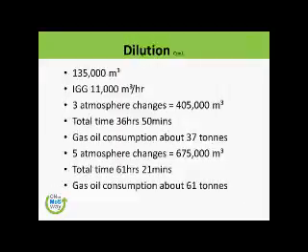So now we have already talked about the displacement process. Now we are giving you some hard facts about the dilution process. In the dilution process, again we are taking an example of the same ship where we spent about 16 tons of diesel and we managed to do the tank environment, pipelines, etc. in 15 hours, 20 minutes.